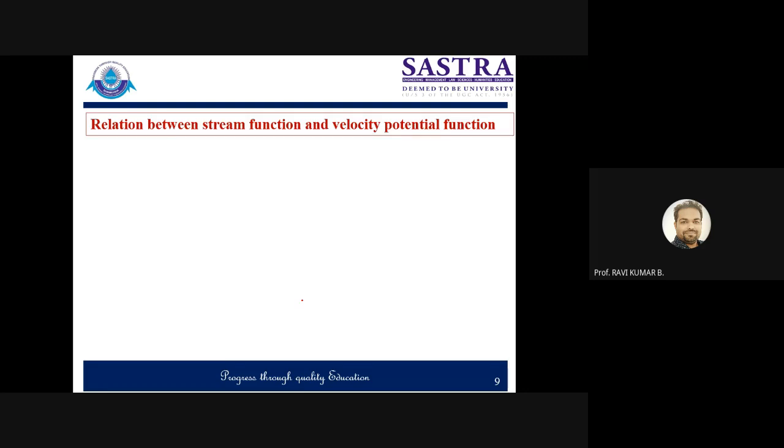So the next topic: relationship between stream function and velocity potential function. How to relate? How can you relate the interrelationship between these two, that we will be looking for. For that, we will go one by one. So the first equation we will write is for the equipotential line. It is a line along which velocity potential function remains constant. A line along which φ remains constant is known as equipotential line.